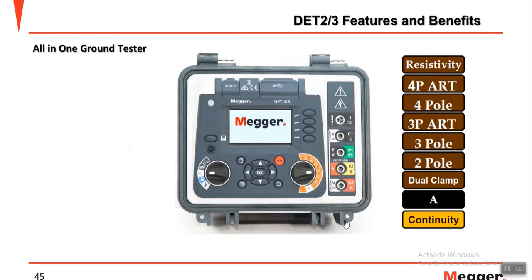And the last topic is the new grounding tester, the DT23, which can do testing based on some methods, or I think all methods. This equipment can do 4-pole technique, 3-pole, triple testing with fault potential or depth measurement, dual clamp-on methods, and also can measure current, leakage current, and continuity. This is a very good instrument because a complete set of methods can be done through this unit.